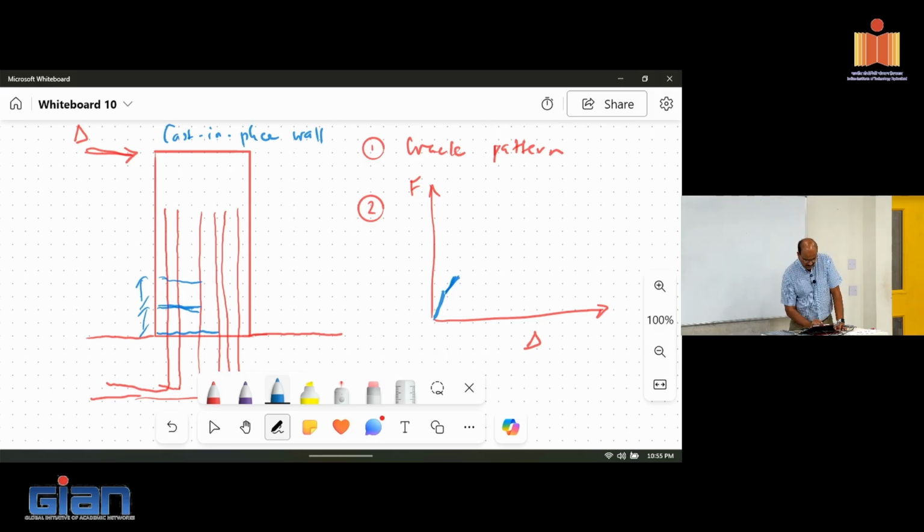You will also start to see shear cracks, or typically the flexural cracks starting to turn diagonally, indicating that shear is also starting to play a part here. This area is where the full contact between the wall and the foundation is, where the compression force is being transferred.